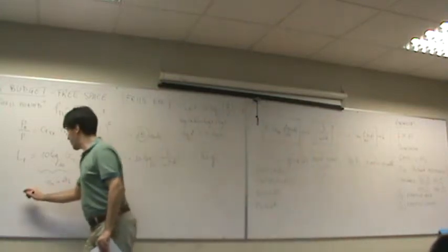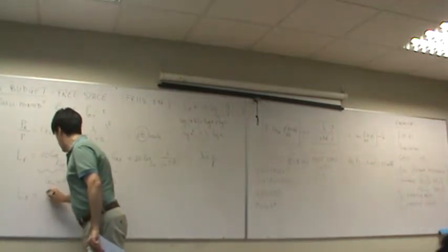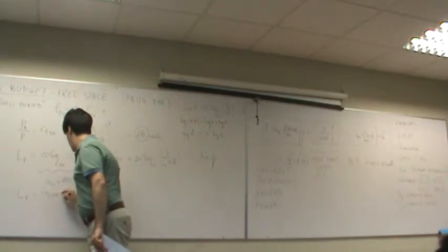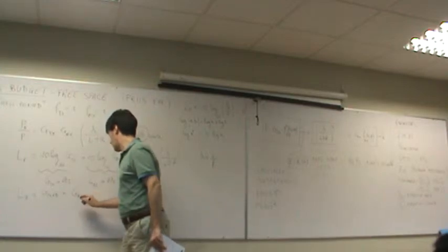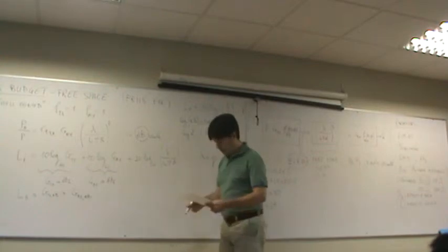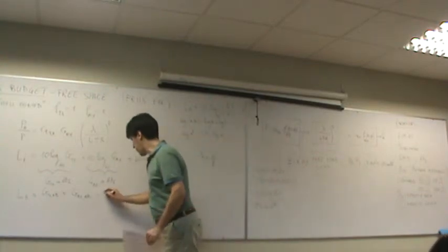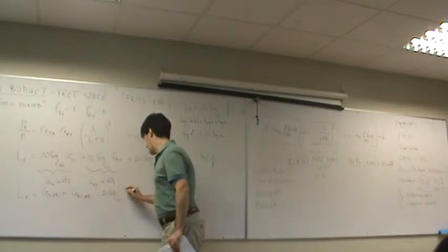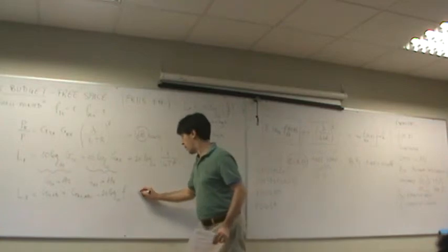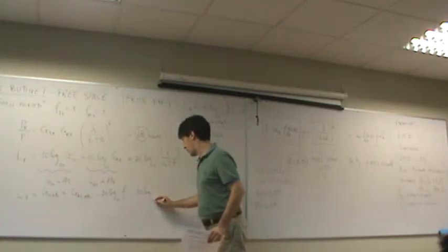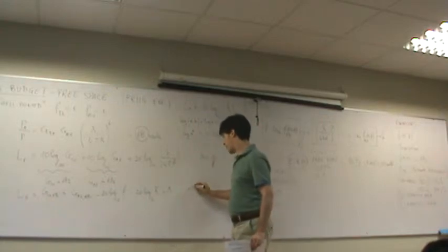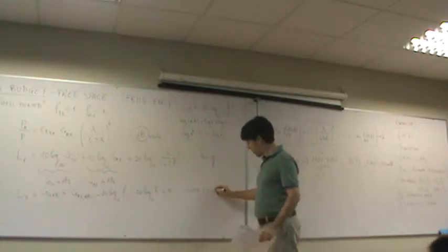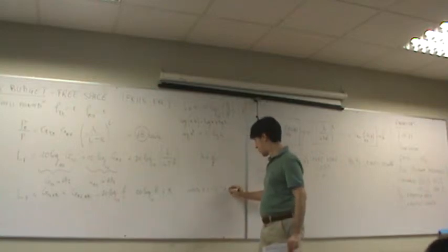So at the end, with a couple of manipulations, you'll find out that the insertion loss is, and then you can express everything in function of frequency, minus 20 log of the frequency minus 20 log of the distance plus a constant k, which is 7.6.